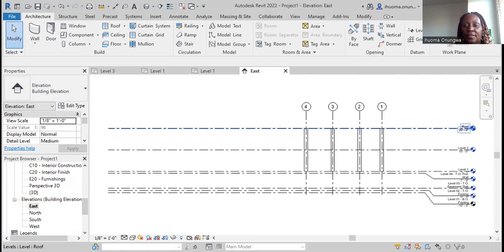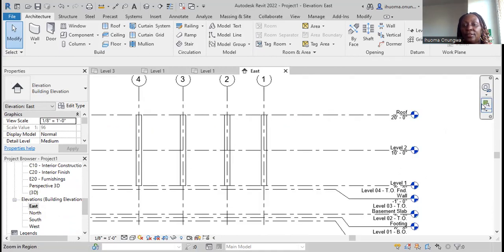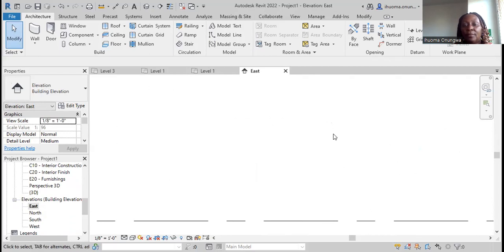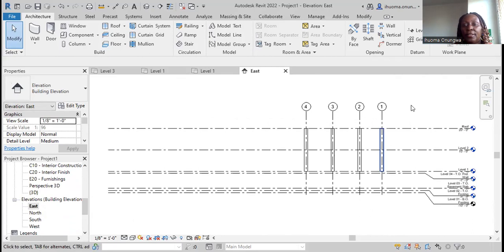I'm looking at it, and I want to say, okay, what is the height of my, this is a construction template. So you already have a lot set up. If it's going to the basement, you can delete the levels that you don't need. But this is from level 1. Height from level 1 to level 2 is 10 feet. Height from level 2 to roof is 20 feet. And this is fine. Assuming it's going above this level, you can create another level.